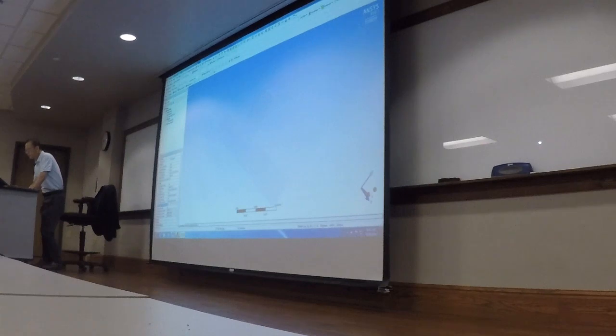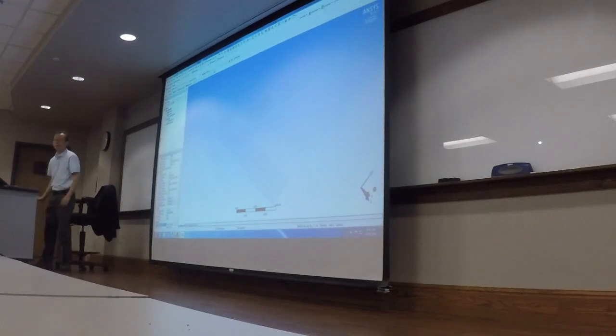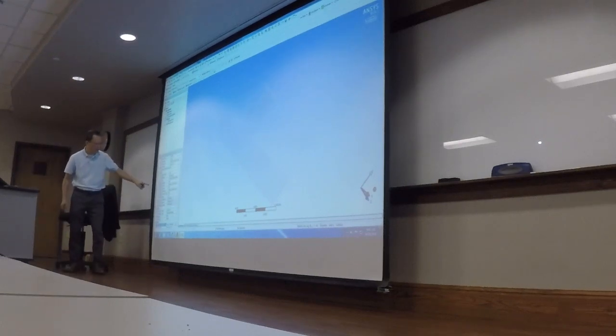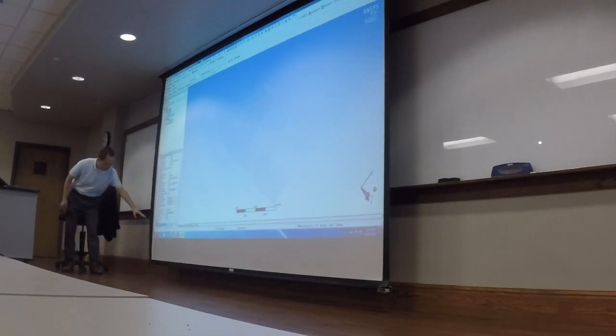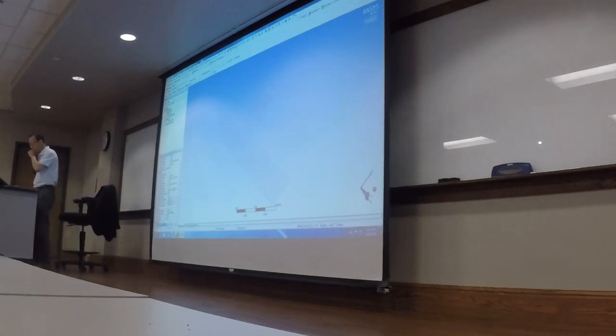Quality, expand quality, smoothing high. Inflation, program control. Right, three things we need to do. Under sizing, change the curvature normal angle to 10. Under quality, smoothing high. Under inflation, program control. So three things you need to change. All right.